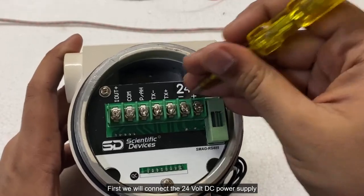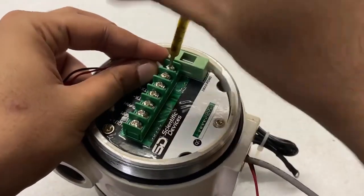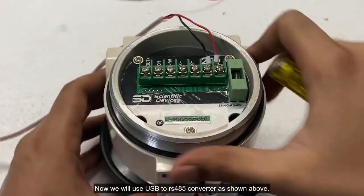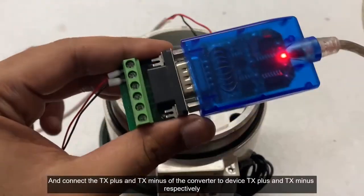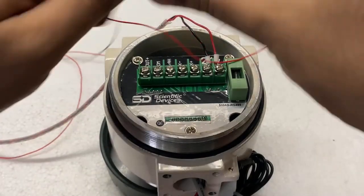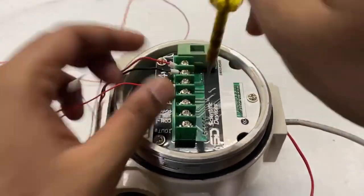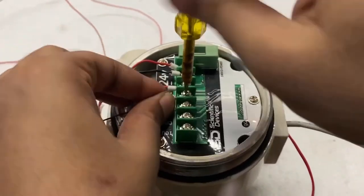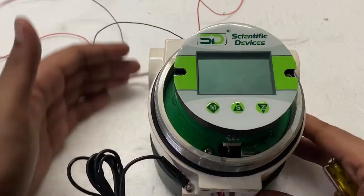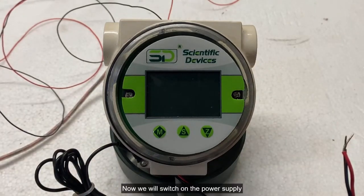First we will connect the 24-volt DC power supply. Now we will use USB to RS485 converter as shown above. And connect the TX plus and TX minus of the converter to device TX plus and TX minus respectively. Now we will switch on the power supply.